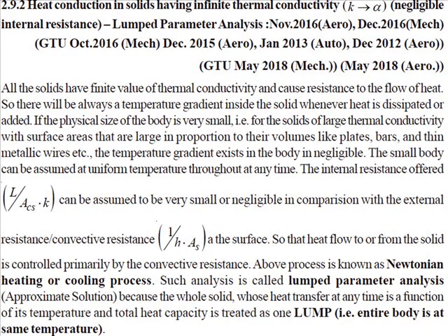First we will discuss what a lump is, and then we will discuss what is called lump parameter analysis. Friend, in the previous lectures we learned that all solids have a finite value of thermal conductivity, and because of that each solid offers some resistance to heat transfer. So we always observe a temperature gradient within the solid, whether heat is dissipated or added to that solid.